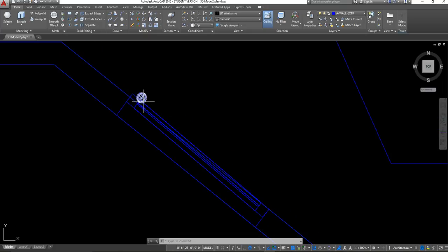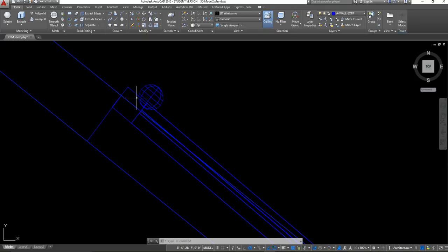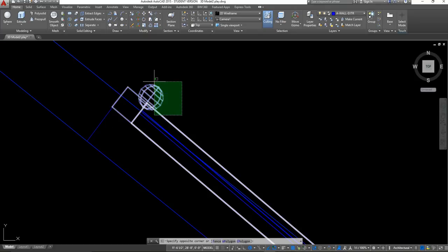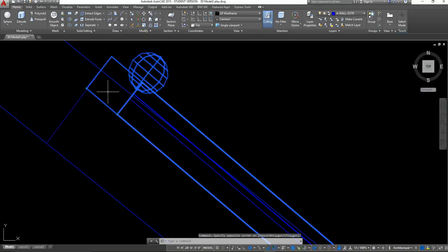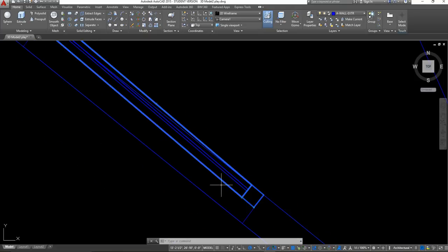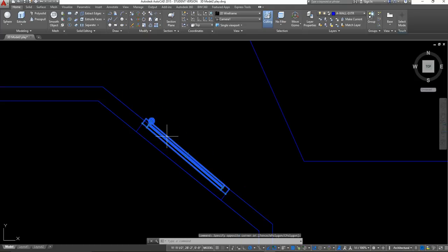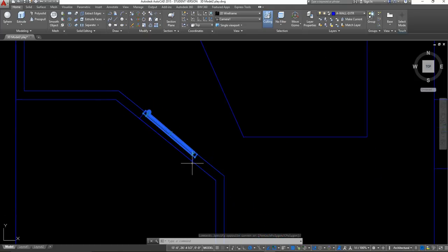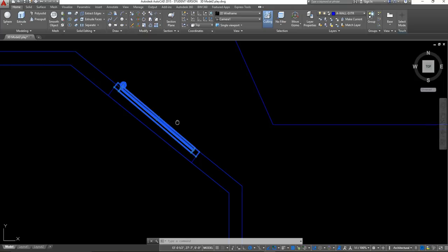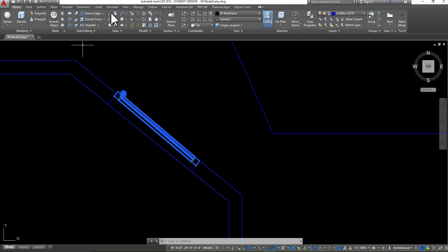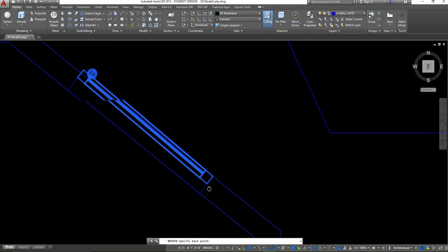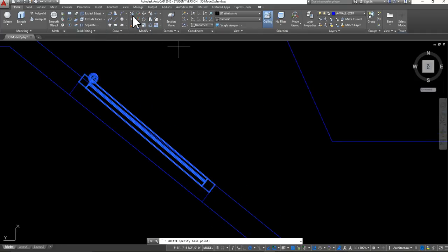It's a little off here, so I'm going to go ahead and rotate it here. So I'm just going to select those elements, and you want to make sure you don't select your wall. So I want to select that, and then I want to make sure I select my panels here in the inside. So I'm just going to go here and just make sure that I selected that. And so you may just have to zoom in to make sure that you're getting everything and you're not selecting that wall too. Okay, so once I have it selected, I'm going to go and get my rotate, and I'm going to select